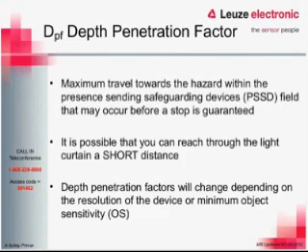So if it's a 14 millimeter resolution, which is finger safe, there is a certain distance that your finger will pass through that light curtain until it actually trips. And this is the worst case scenario that we're looking at, that you are between the beams equidistantly, and you can maybe get a quarter of an inch in there before you actually trip it. So again, with most safety calculations, we need to look at the worst case scenario.